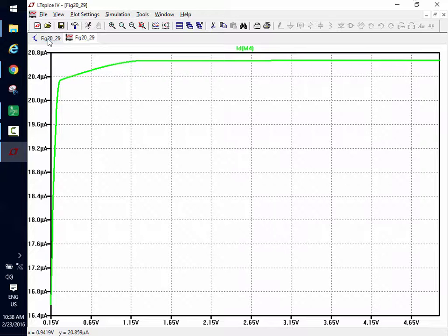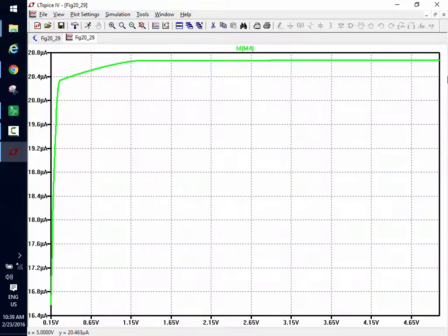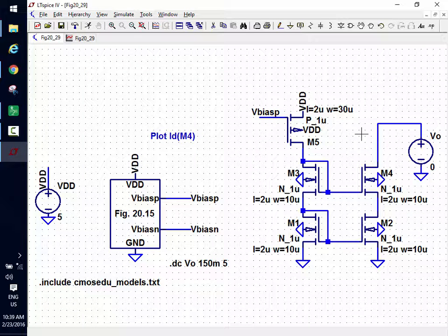Does everybody see that this voltage here is 2 VGS? I got a VGS and a VGS. So this is 2 VGS, and so this voltage is VGS, assuming we're in saturation. So I need a VGS here plus a VDS sat here, to keep everything in saturation, to have that real high cascode output impedance. Does everybody follow? So that's a problem, right?